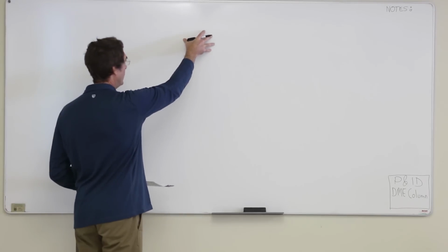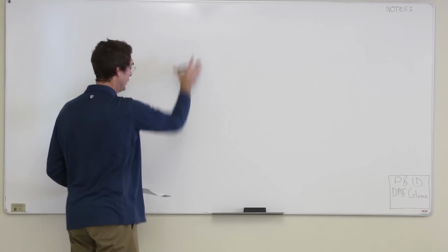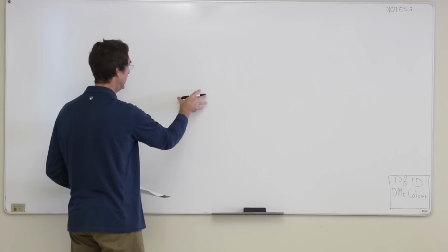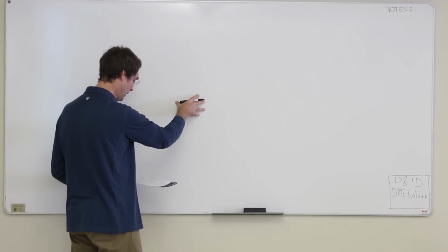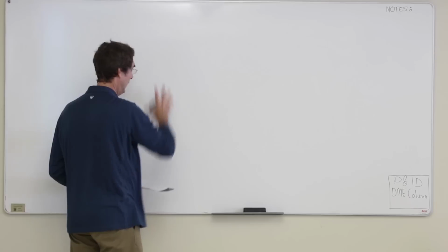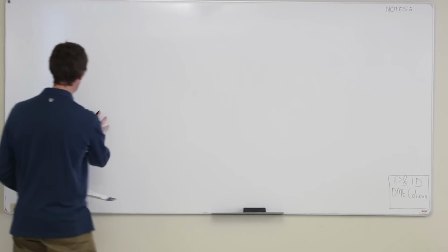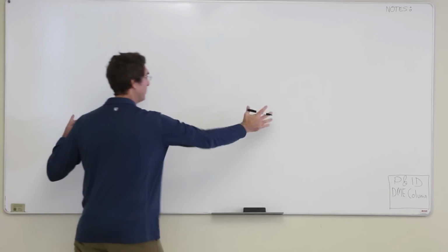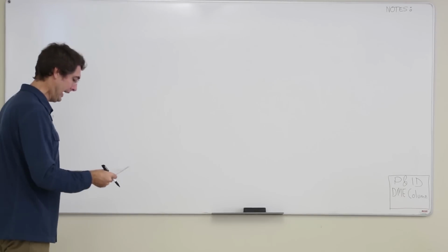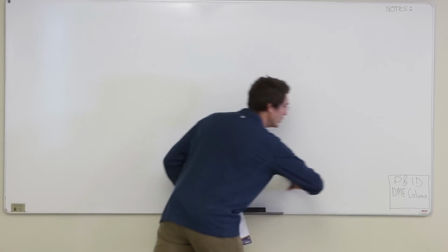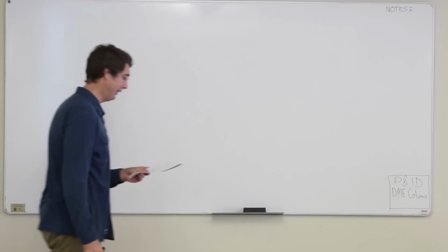I'm going to come over to the condenser here. It's going to have to be fairly high because I want to get the pumps down in here. And I need the reflux drum in here, and there's tons of controls around the top of the column, as well lots of controls around the bottom of the column, so I want to spread stuff out a little bit. And I want lines to be able to flow off the P&ID fairly easily.